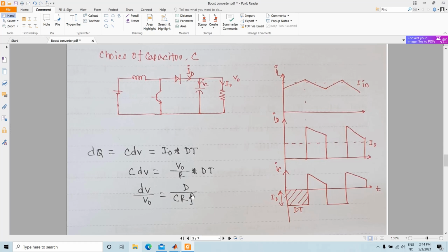And normally, you try to adopt the switching frequency at a higher value. The reason is that the higher the switching frequency, the smaller the dimension of the magnetic circuit, or the inductor, will be.